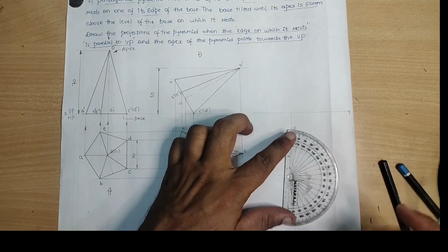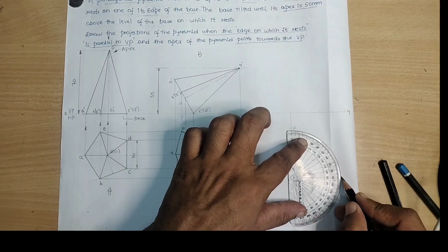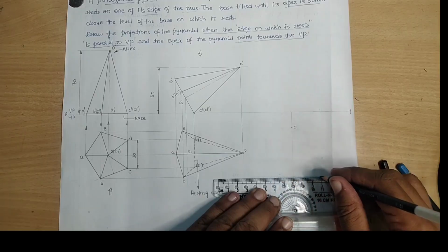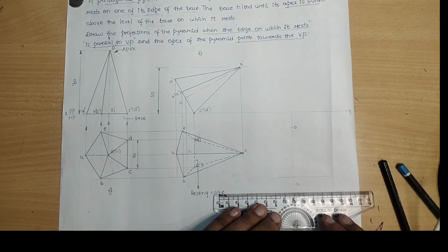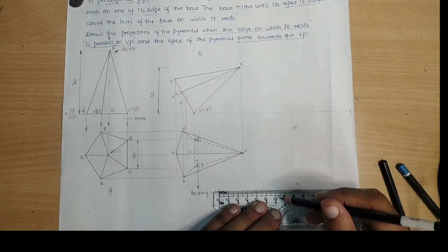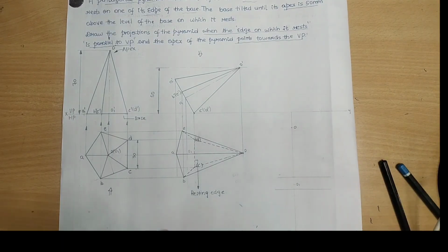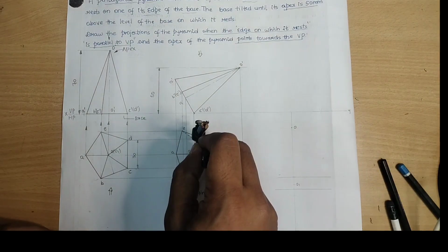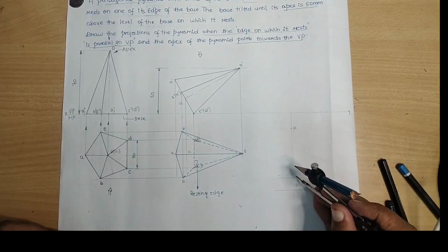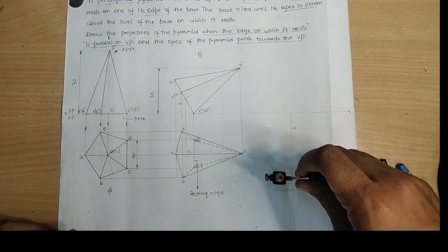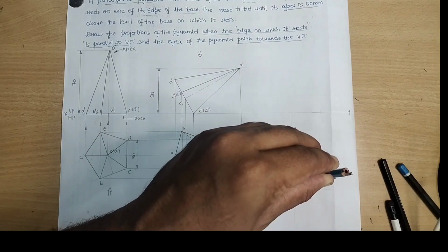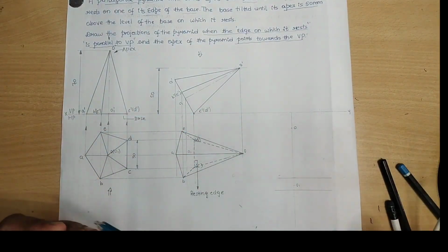Meanwhile, I will make use of the protractor. I will mark 90 degrees, something like this. I will draw one line here, followed by one more line at this point, and the last point I will keep as it is. Now make use of your compass. This imaginary point as the center, take the distance up to the point D. From this point cut an arc so that you get the point D, and on the other side cut an arc, you get the point C, or any other method of transferring the points you can do.